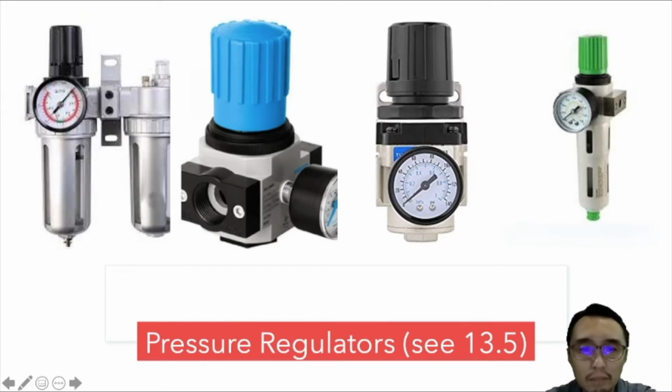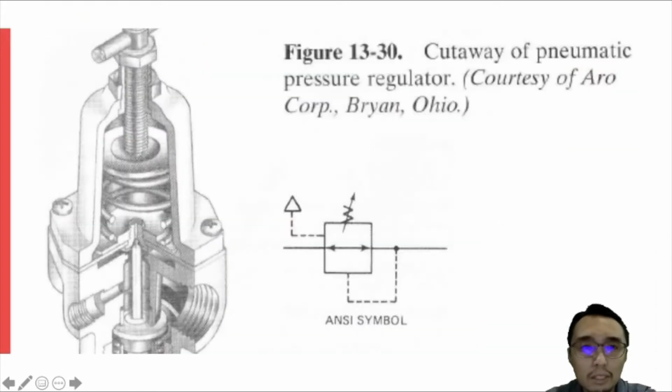A cutaway view of an actual pressure regulator is shown here. Again, we have discussed the detailed operation of this in section 13.5. The desired pressure level is established by the T handle, which you can turn to establish the pressure level required.